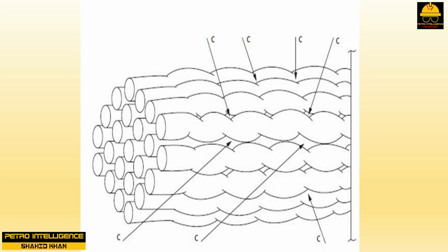that in manufacture of the bundle, the tubes must be grouped or lined up in the bundle so that the ridges do meet and touch to form the curved points of contact described above. Also, and most significantly, this alignment produces shell-side cleaning lanes at various angles all the way through the bundle between the ridges on the tube surface shown in the picture.